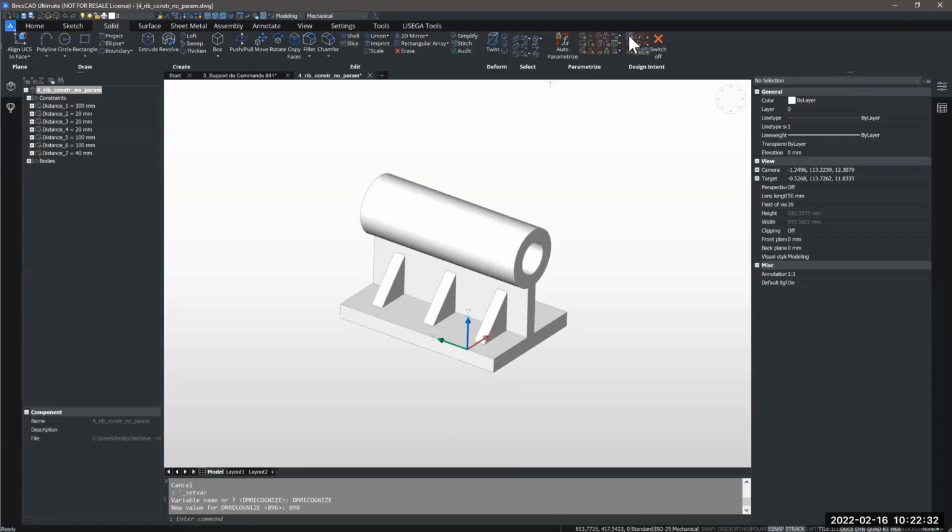First off, I will enable coincident planes so that all planes that are attached to each other will keep the relationship between them. And I will go ahead and create a new parameter. I will give this parameter the name of W. It will be a lot of numbers and a lot of different letters right now, but once you are doing this yourself, it will make more sense just following the guide.